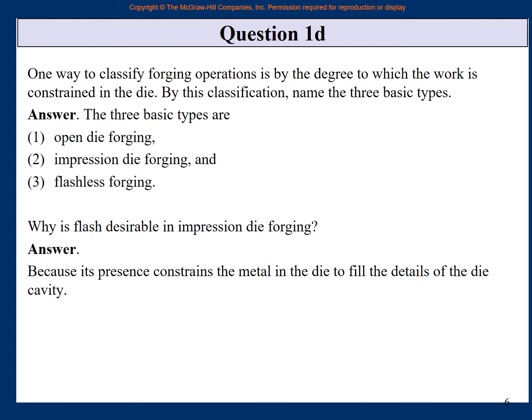So compare it to casting. You pour the metal inside the mold, it is completely full, but maybe afterwards it will shrink. So how do we make sure that after cooling it will still be the full size? We make a riser after the mold cavity. So material initially fills completely the die cavity and then rises into the riser. So some extra material is now there. So even if it cools and shrinks, there is extra material there and it is completely filled inside the mold